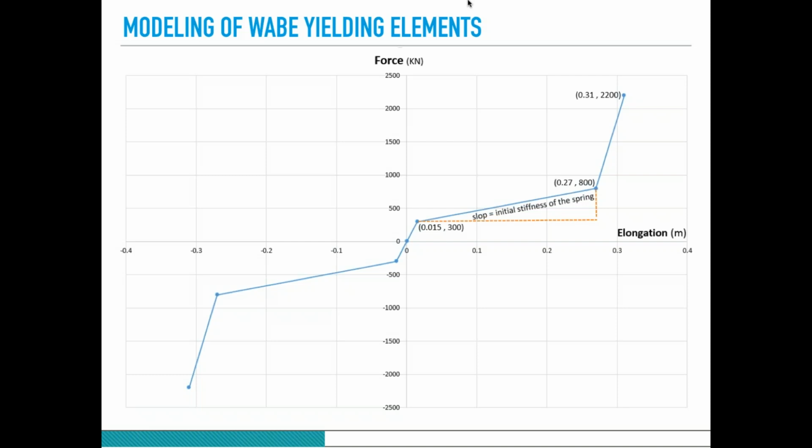First, I decided to use the interface. So between two parts of the tunnel lining segments, I applied an interface to model this deforming capacity. But actually, the results didn't satisfy my expectations. So I decided to use nodal springs, which was really successful, and I recommend you use them first.